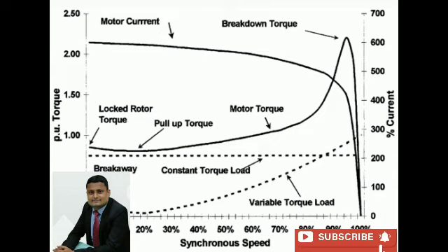Corresponding to the operating flux density in the stator teeth, iron loss per kg of the material can be found out from the graph, the flux density versus loss graph. So multiply this specific loss value with the total weight of the stator teeth. So that gives the core loss in the stator teeth.